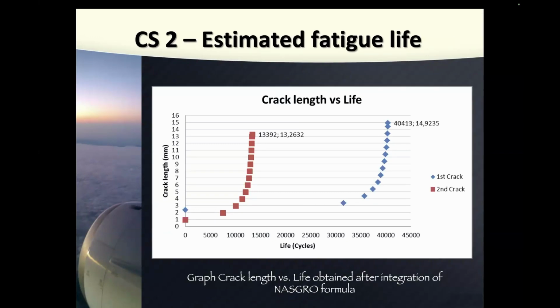Okay, again, using the previously described approach, I got for the first crack a life of about 13,000 cycles, and for the second crack 40,000 cycles. By the way, we stopped the experiment after 56,000 cycles. We used a very high load because we didn't want to wait for days to get the crack. Honestly, we did not expect it to be finished in less than 1 hour. We estimated 2 to 3 hours, but we completely destroyed the spar. It was 3 hertz, so 3 cycles per second. So we can calculate easily what 58,000 cycles is.